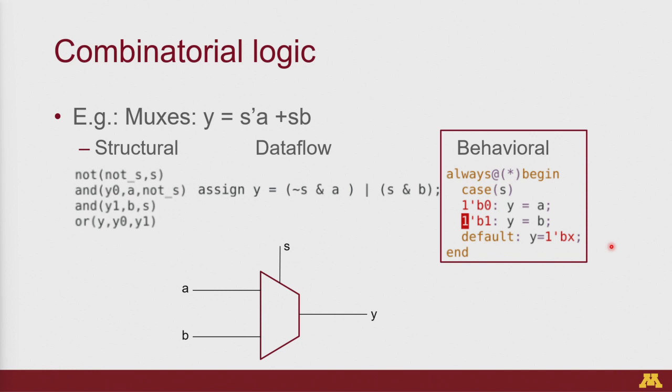But in pure Verilog, with always @(*), it will just assume you wanted a latch and make a latch, because that is a legitimate and legal way to design latches. In Verilog, it won't know your intention, but in SystemVerilog you say whether it's combinational or a latch. Right?